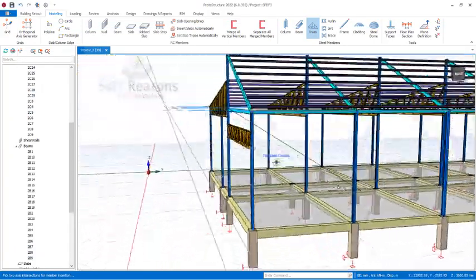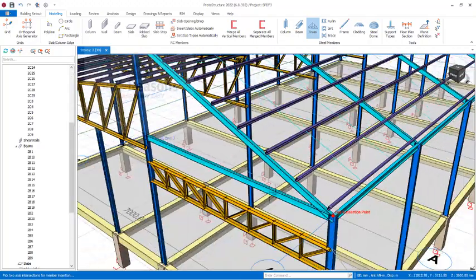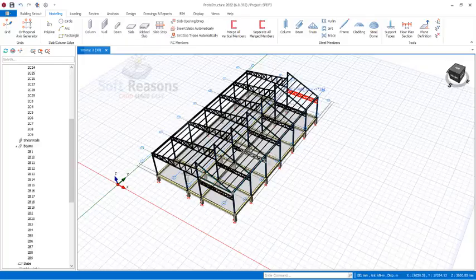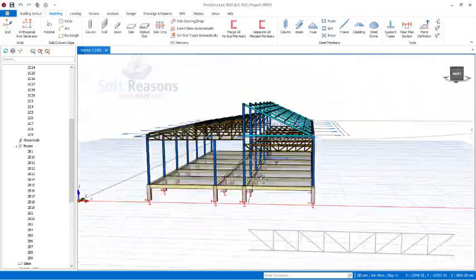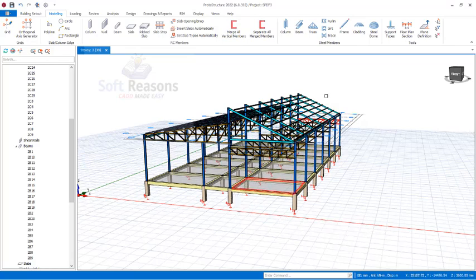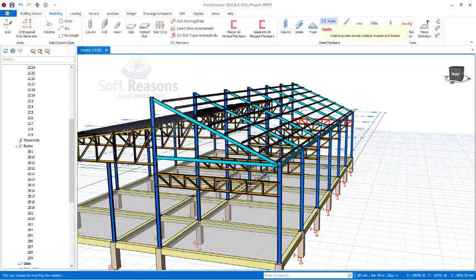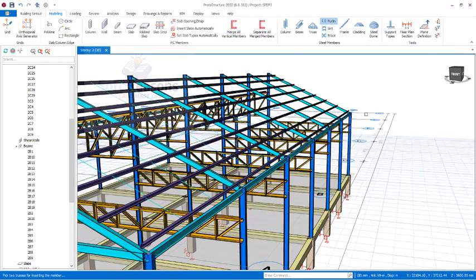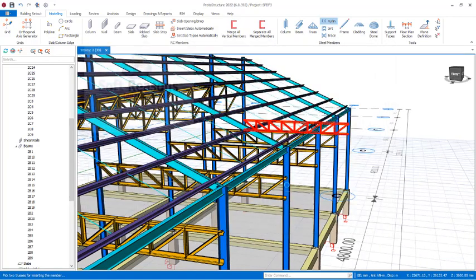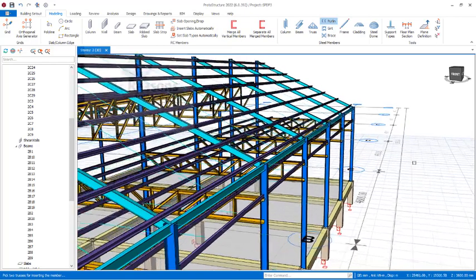You can see. So the same way we have to proceed and place it in other provisions successfully. So you can see now we have placed that successfully. You can see over there. All right, so I'll have to deselect this command, and then I'll pick the purlins again. We have purlins on these trusses. This will help us to provide a kind of platform right there. Click on the OK options to have purlins on top of that, just like this.